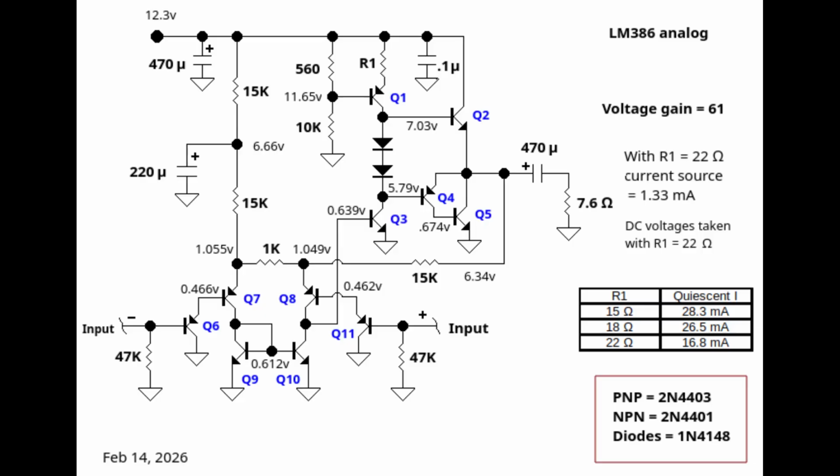The voltage gain of the LM386 can be set between 20 and 200, which is 26 and 46 decibels. Right, let's discuss Q9 and Q10, which provide the collector load for the emitter coupled pair. In my opinion, Q9 and Q10 are the heart of the LM386 and allow the output rail to lie at half of the set DC voltage, plus facilitate the impressive clean output power swing that we enjoy with the LM386.